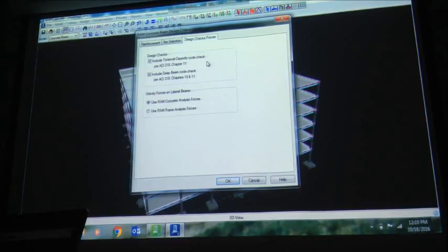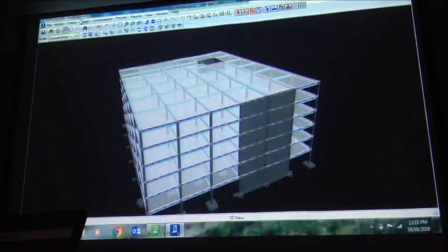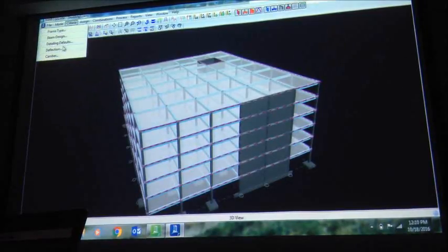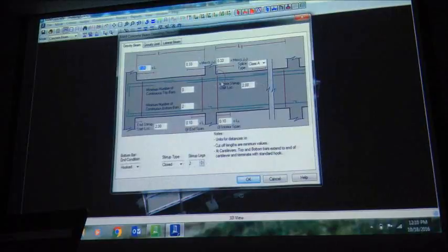Remind me in our regular class what are the torsional checks and deep beam checks. You will see that all the edge columns or edge beams will fail due to torsional. Okay. Assign beam detailing. This is how it will detail again. It's a complete thing. Minimum number of continuous bars on the top is, I will make it 2. Okay. This is a column support, so where they want to place bars and how they want to place bars. This is what it is. Lateral beams, usually I will give 2 also. Okay.